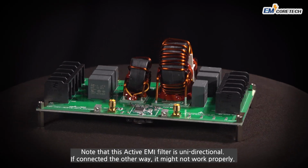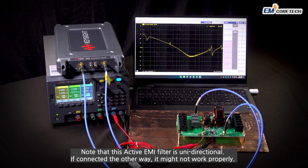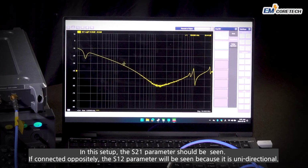Note that this active EMI filter is unidirectional. If connected the other way, it might not work properly. In this setup, the S21 parameter should be seen. If connected oppositely, the S12 parameter will be seen, because it is unidirectional.